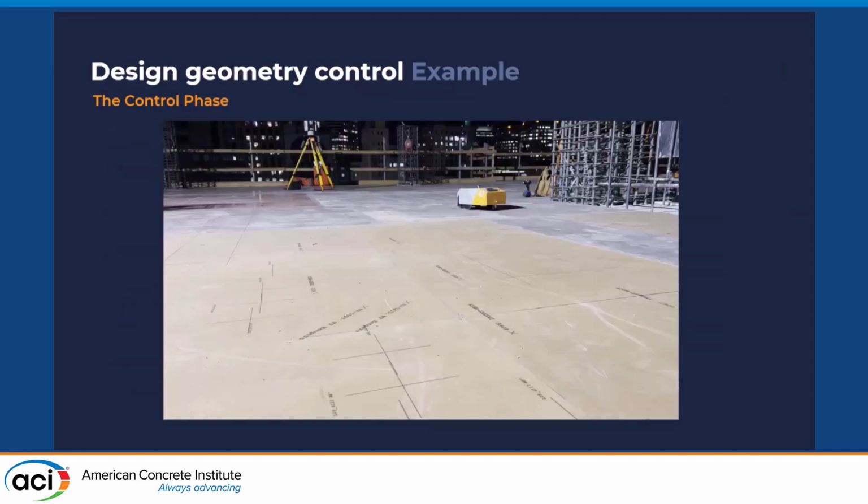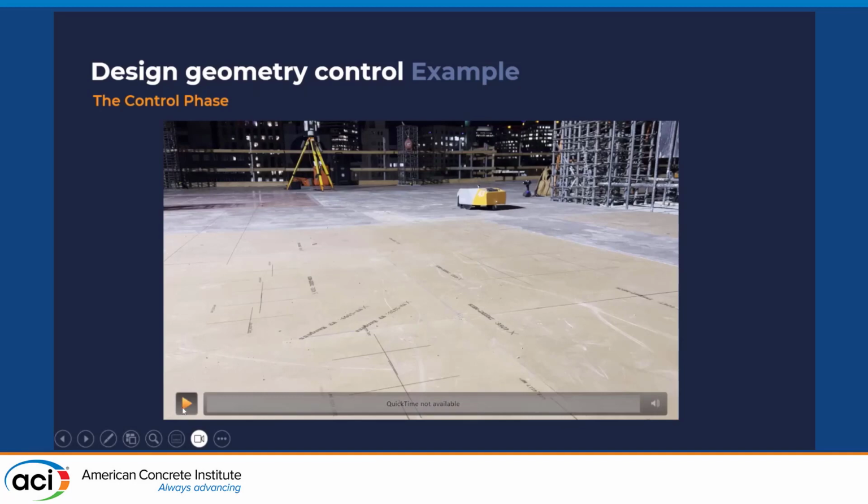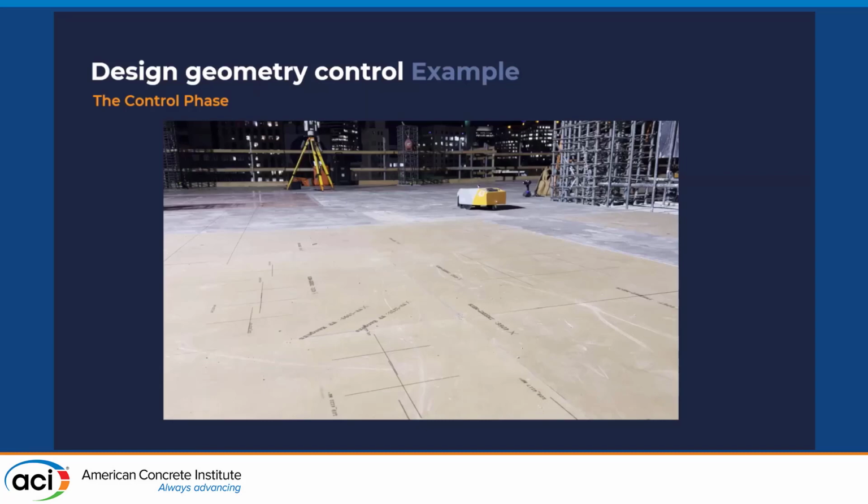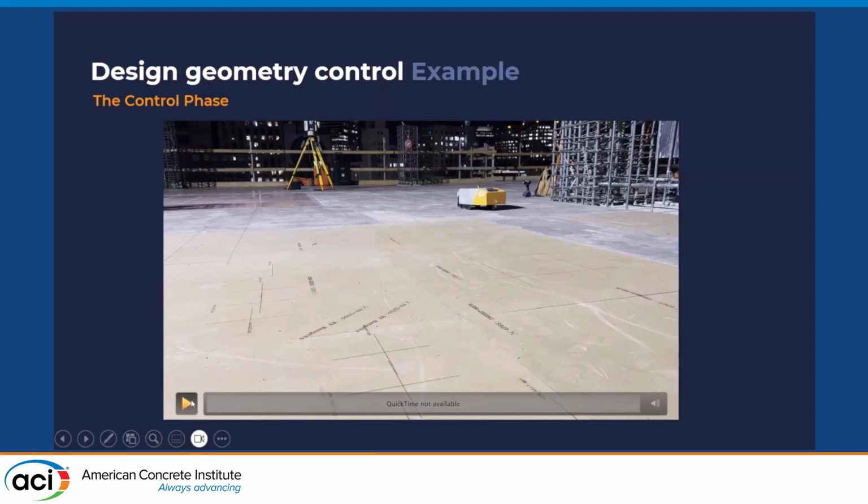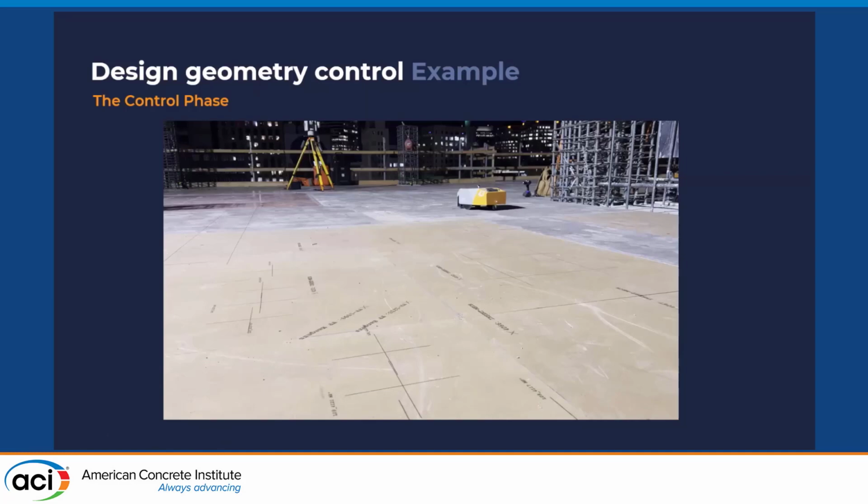What's the outcome of that? We can actually use layout technology today that prints this entire drawing in like 4 hours on a plywood deck. We've done this on a project that we worked on with Kerry on 1900 Broadway. What I want to say with that is that we now have a drawing that I can use for quality control.